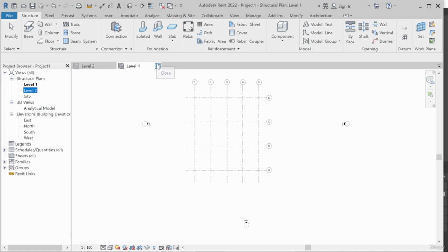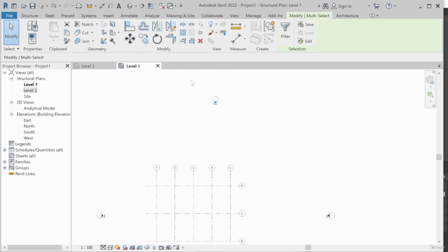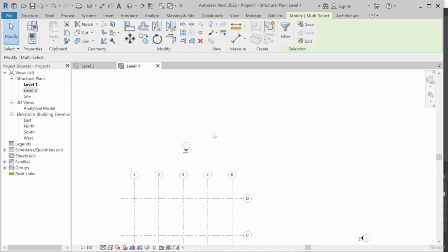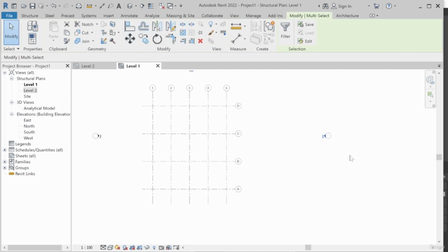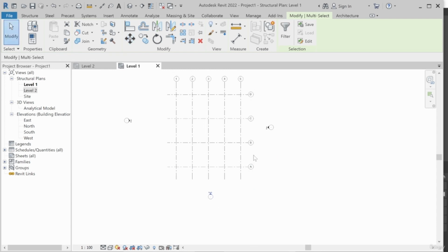Okay, now what I can do again is I can decide to move this. So highlight it, come here, move. You can see the shortcut MV, so you can move it to whichever location you want. And I can move this with MV to whichever location I want, and move this to whichever location I want. Sorry, escape, then MV to move to whichever location I'm convenient with.